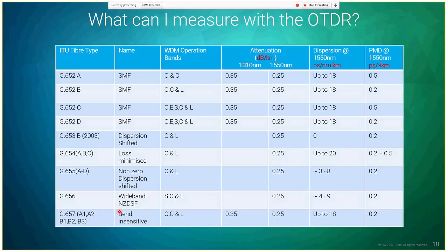So all of you working on customer houses, that need to do corners and all those installations which are very difficult to do indoors, for more diverse applications, you're going to be using the G657. And the G657 had a price much higher than the G652. With the intensification of FTTH and the demand, the G657 has been decreasing in terms of price. So I even have customers installing the G657.